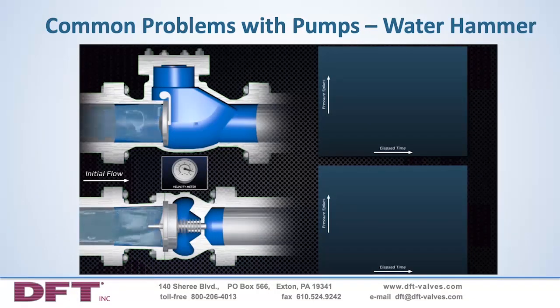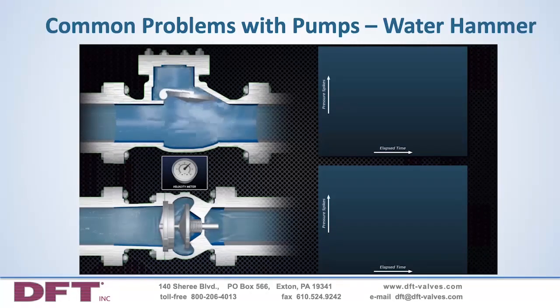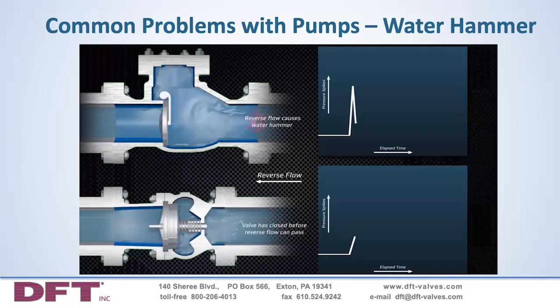A common problem with pumps is water hammer. Water hammer is a shock wave that is transmitted through a fluid that's contained within a piping system. The most basic explanation is that water hammer occurs when a fluid in motion is suddenly stopped or forced to stop, either by the shutdown of the pump or the sudden closing of another valve.